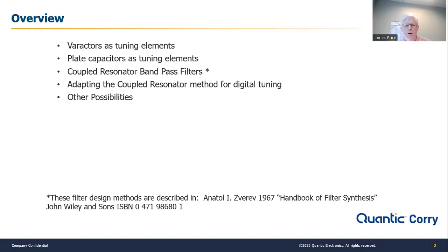Sure. Hello, everyone. So the topic today is tunable filters. I'll be mostly talking about bandpass and band reject filters. Low pass and high pass filters don't seem to be as much of a concern when it comes to tunable filters. We'll get right into the popular tuning elements for these kinds of filters. Varactor diodes and air core plate capacitors are two possibilities. We'll talk a little bit about those.